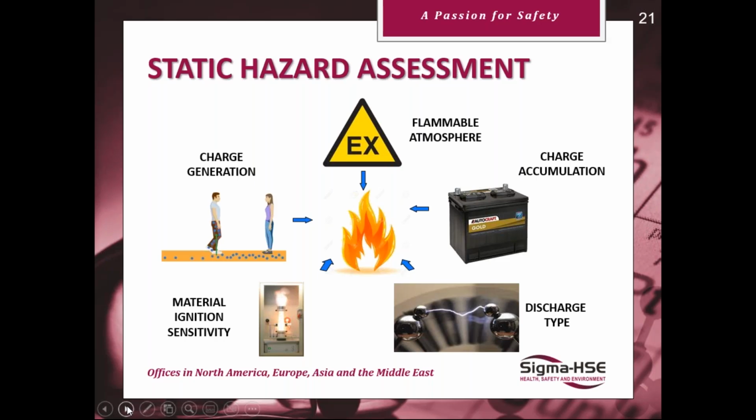But if you work within the flammable range, you will have. Powders, near enough impossible to stay out of the flammable range unless you can manage to keep it below the MEC, the minimum explosive concentration, but they're not homogeneous, so they tend to send slugs of powder through a system which is within the flammable range.